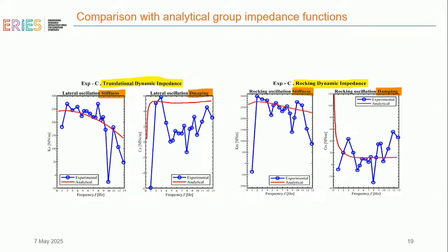This is very difficult, actually, because we didn't capture the damping, because of the nature of the way we are running the tests. The problem is that our force and our response do not have a common time. Because we are outside in the field, we are not able to plug all instruments that produce the force and record the response into the same data acquisition system, which means that there is a certain time lag that we cannot actually capture.